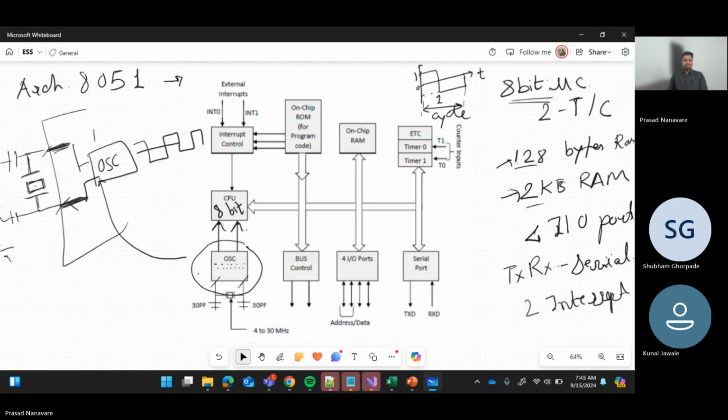Yes, sir. Okay, so a crystal is there to generate a frequency, and we have to convert it into a clock cycle, and that's why we have an oscillator circuit in place, which is embedded inside of the chip. You don't have to do it externally. The only external thing is the crystal part. This thing we connect externally. This is how it actually is, more specifically. So, understood. Now we'll move on to a further part.